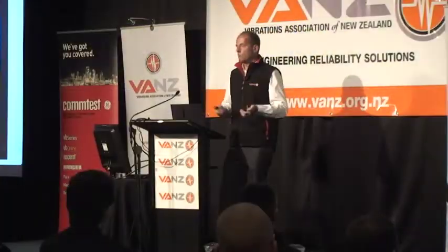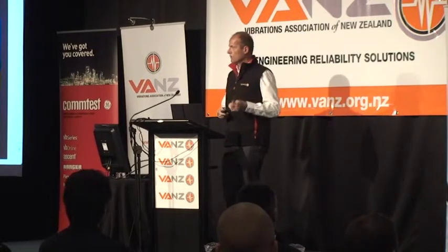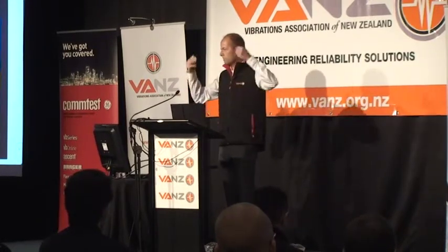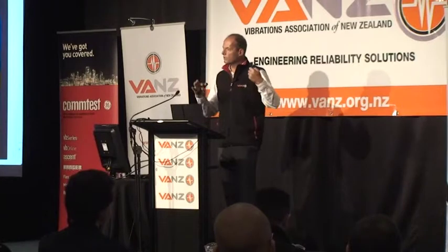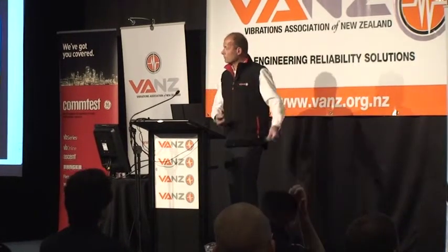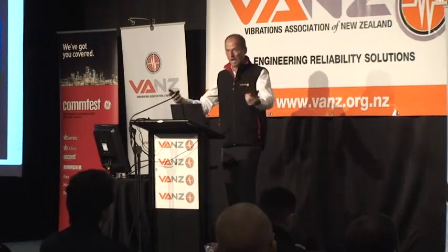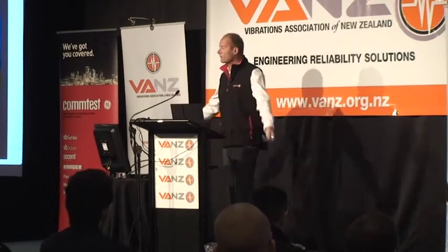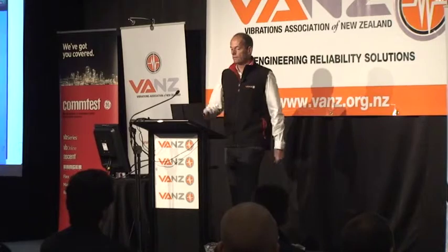doing phase analysis. We can see if it's that circular motion. We can see if it's pushing, pulling, bouncing, swaying, rocking, twisting. We can learn all about that and relate that back to what the machine's actually doing. What is actually wrong with the machine? What do I have to fix? How quickly do I have to fix it?